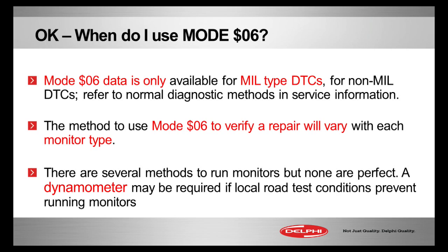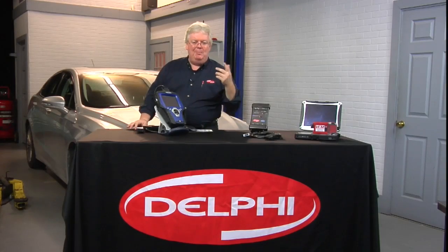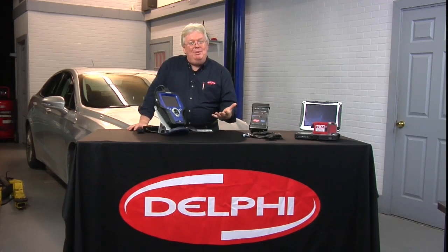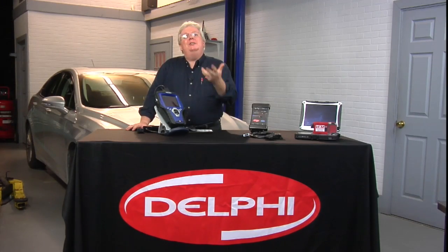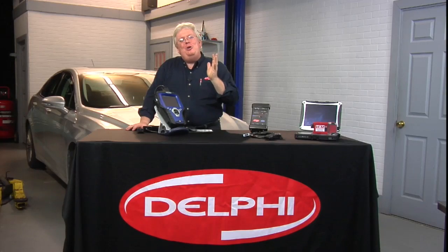Like I mentioned with the example of the catalytic converter efficiency. You can verify if the cat's working, if you do replace a cat, by running the monitors and seeing where that falls into the minimum and maximum specifications. Now, also keep in mind, and I understand your pain on this, I do a lot of classes in big cities, and the techs look at me and go, yeah, run the monitors, right? In this neighborhood, I got to drive a half hour to get an open road. Or in New York City, it may be 2 hours to get a good open road.